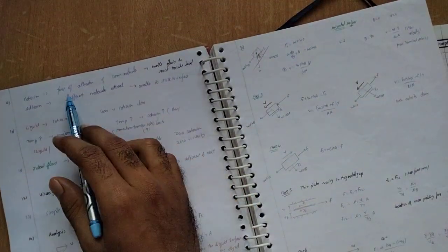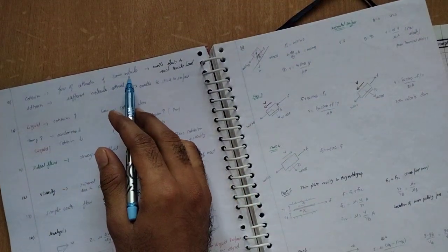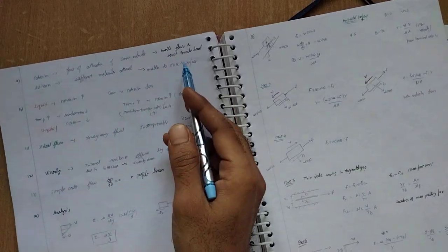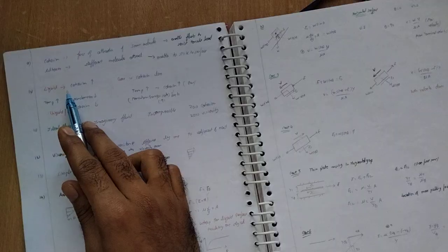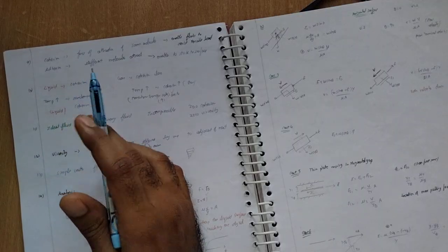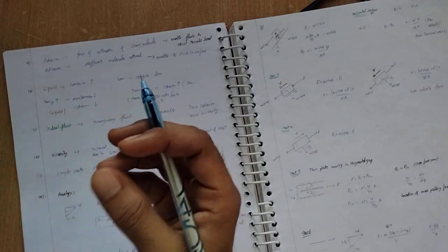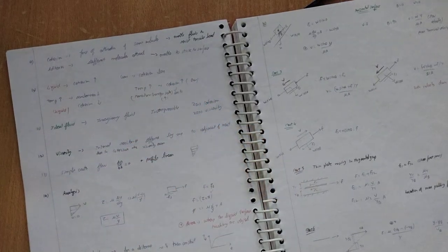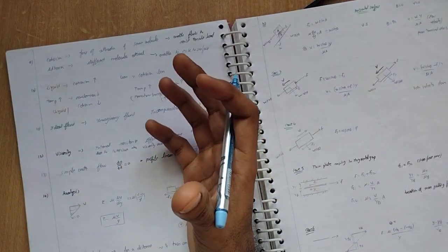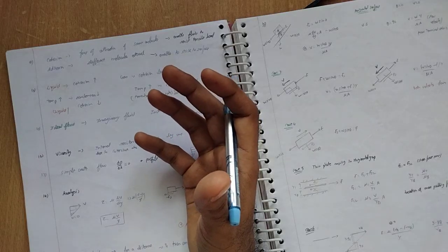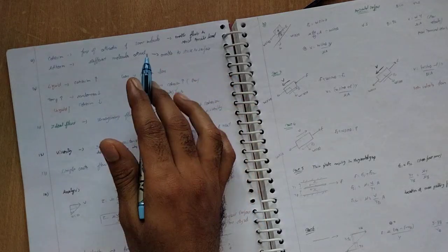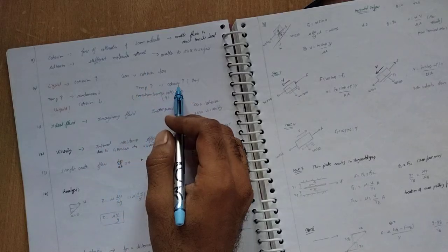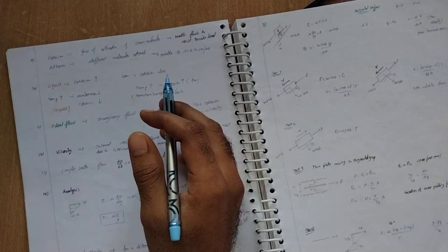Next, cohesion is the force of attraction between same molecules, which enables the fluid to resist tensile load. Adhesion is the attraction between different molecules, enabling them to stick. In liquids, cohesion is much higher because of same-molecule attraction. Whenever you heat the liquid, the cohesion starts to decrease. But whenever you heat gases, the cohesion starts to increase. Normally, for gases it is much lesser, but when heated it becomes much higher.